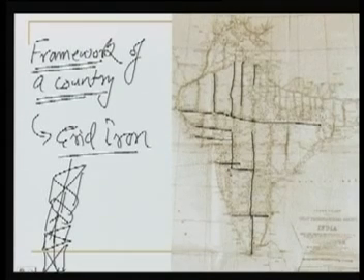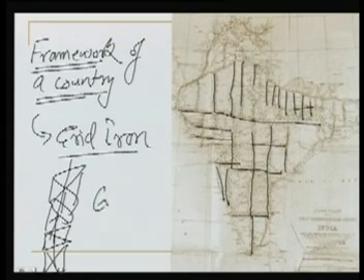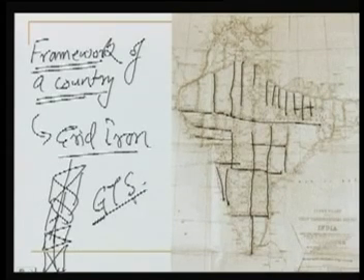So this kind of framework, which is generally useful for a large country, is called the gridiron system, as it appears as if there is a grid, and by this grid the control points are established everywhere throughout the country. This is also an example of the Great Trigonometrical Survey of India, a survey which started some 200 years back, and starting from somewhere in Chennai, Madras, this network was established throughout the country, and later on more triangulation chains were established and the network was completed.